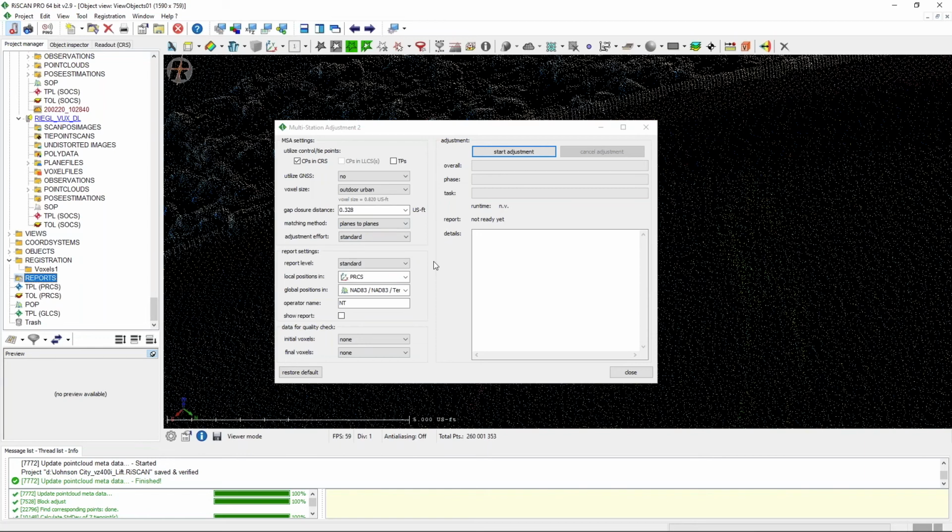We talked about the importance of Joseph's Manager and where it needs to be if you're using it. We talked about some of the options in AR2, which is automatic registration, selecting the different scenes and also explaining a little bit what the voxels mean, and then customizing the voxel sizes if necessary. If not, just select the proper scenario, and it then determines the voxel size based on the first scan position.